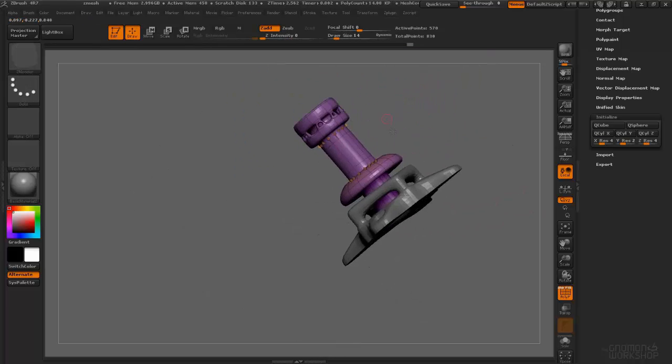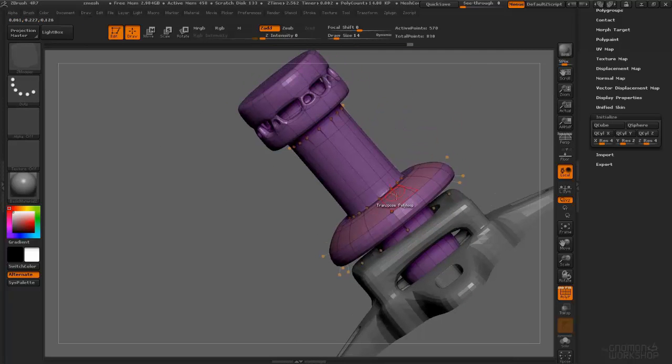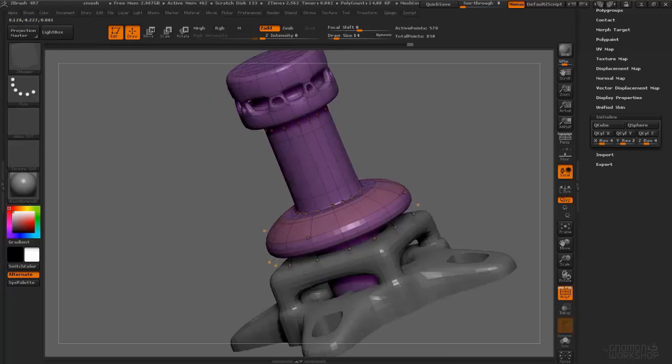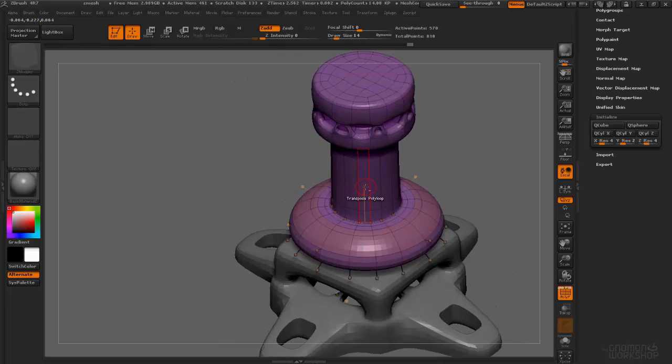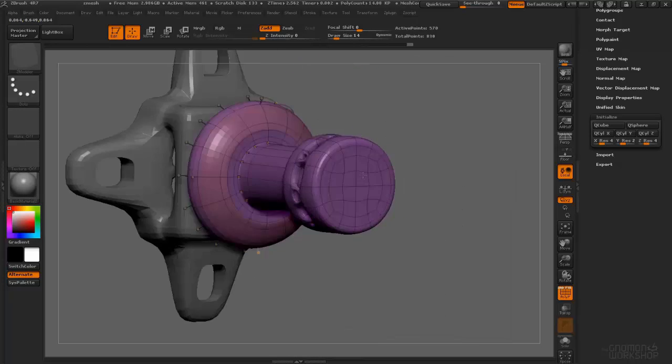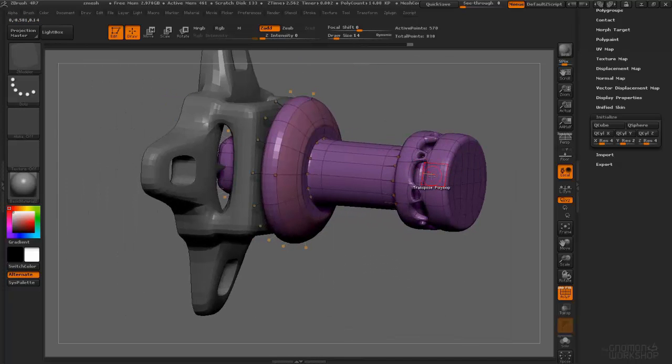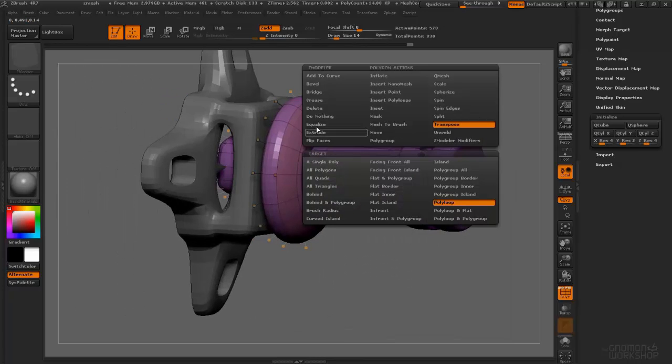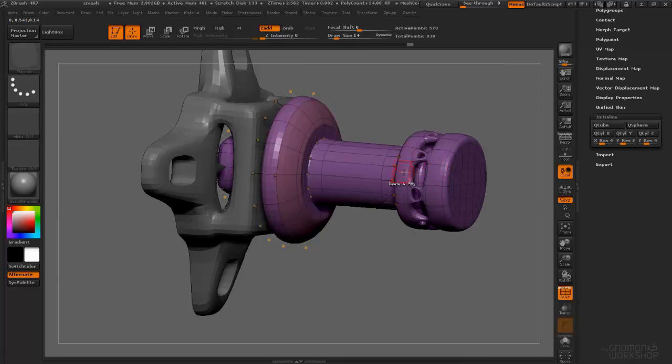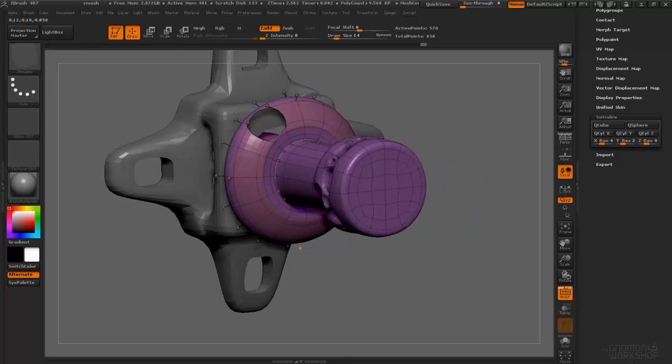So now what I want to do is I want to create some bridges. I want to delete a hole here and delete a hole here and then bridge between the two shapes. So ZBrush, ZModeler here, has some bridging tools which are actually really powerful and quite cool. So just as an example, let's go ahead and see about deleting this face here. I'm going to go to Delete, and I'm going to delete this face and this face. Now I'm going to go to my edge selection, and it can be hard in this mode, as you can see, to sort of select the right edge.